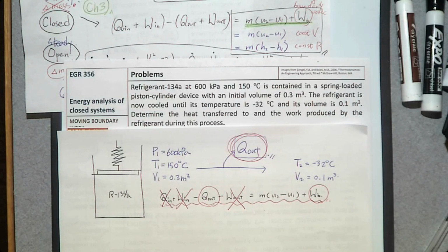So it's a phase change material. So we have to evaluate U1 and U2 independently by using property tables, determine its phase, and then go to a proper table, okay? What about the mass? Oh, we also need to evaluate the mass because mass is not given.